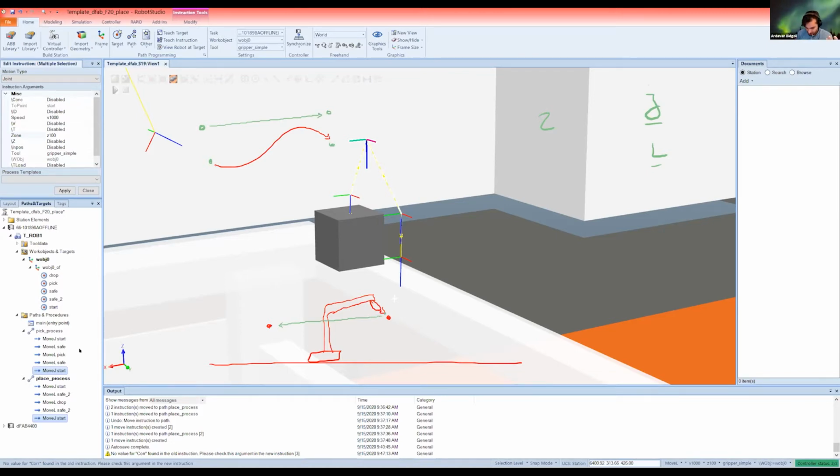On the other hand, if you just use a Move J command, this robot actually makes a motion like this, and gets from point A to point B without any problem. You're going to see it a lot. In the lab on Thursday, when we go there, I will do the same thing with Move L and Move J, and you will realize how much smoother, faster, and more controllable Move J is.